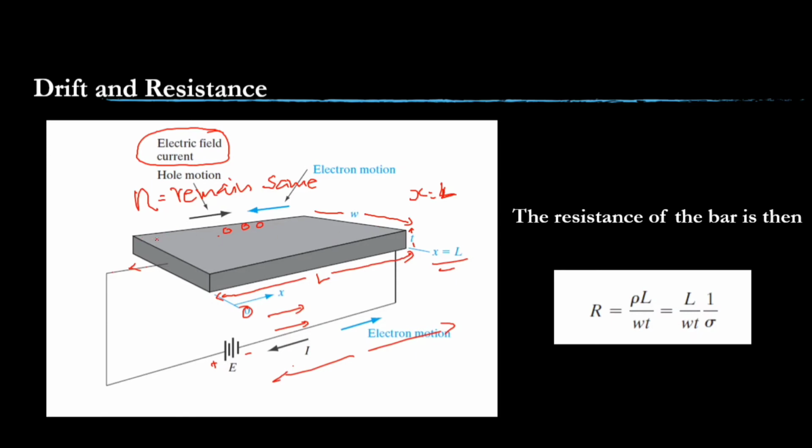So the hole disappears at this point, and holes will be generated at the other end. What I can say is that the current flow in the external circuit is because of electrons, and the current flow inside this semiconductor is because of holes. You can see the hole is moving from this side to there. Basically an electron is jumping from one hole position to another and reaching this side. The hole moves this side and recombines with the electrons here. In a similar way, holes are generated at this point. That is what is written here.